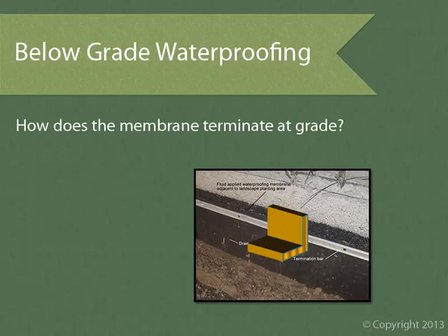Clearly, we need to have this solution before the below-grade membrane is installed so the waterproofing sub recognizes that they need to run their membrane higher than usual. If we find this problem when the facade sub goes to install these angles and finds that termination bar is in their way, it's going to be too late. That membrane will already be cut where it is and it can't easily be made longer.